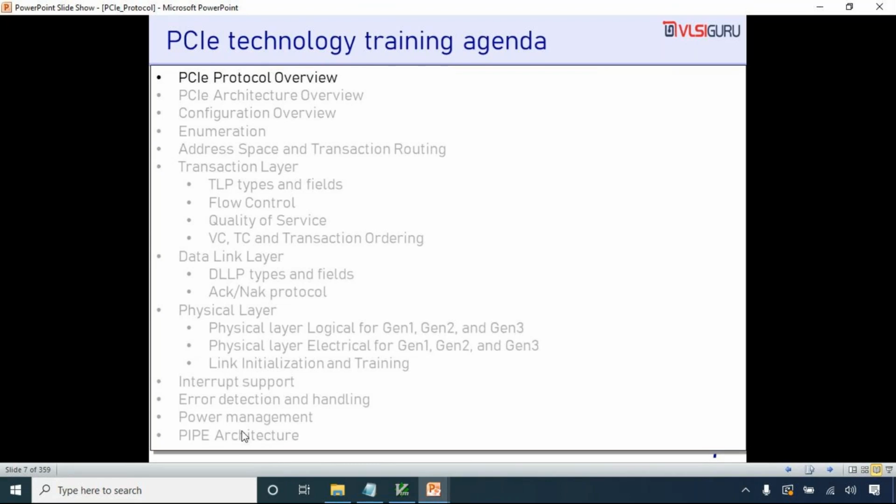When we start off with the NVMe training, there we learn the difference between NOR flash and NAND flash. You will realize that NOR is quick to read, but slow to write and program. NAND is good at writing, and NAND is also more efficient in terms of memory footprint. You need more space per bit for NOR flash, and less space in NAND. That's a very brief overview of what we are talking about.